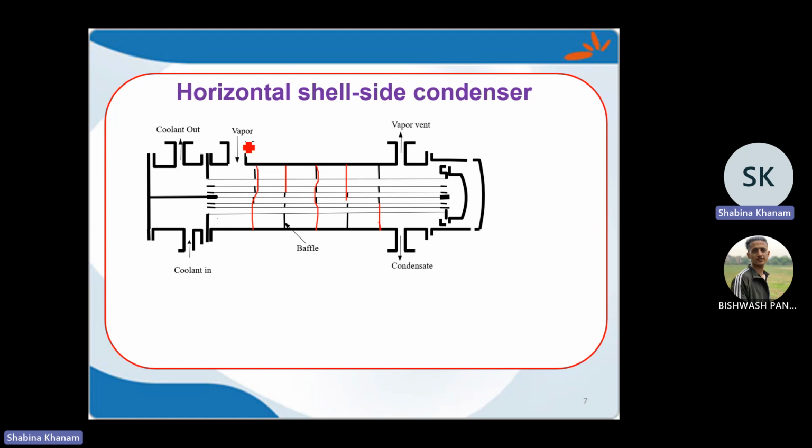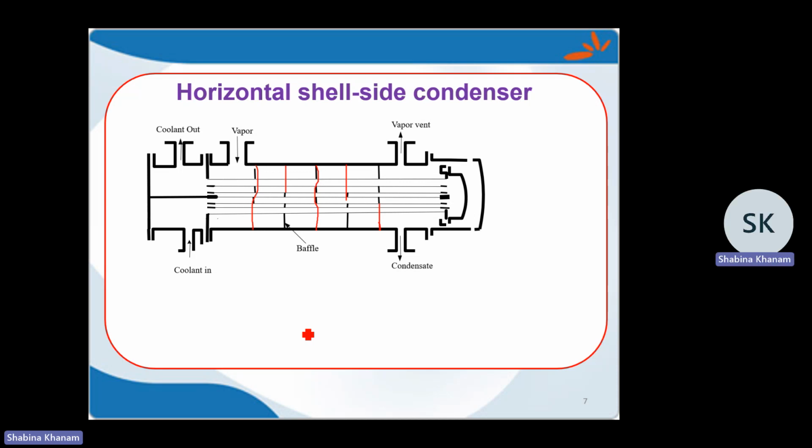Now, if I consider the vapor here, the other side of this vapor has another unit, and that we call the vent. The purpose of this vent is that when the operation is not being conducted, we usually have air in this shell side. So when we inject the steam, that air has some volume, though it will keep on compressing, it will accommodate some of the volume, and the heat transfer area would be lost. Those gases or air we consider as non-condensables.